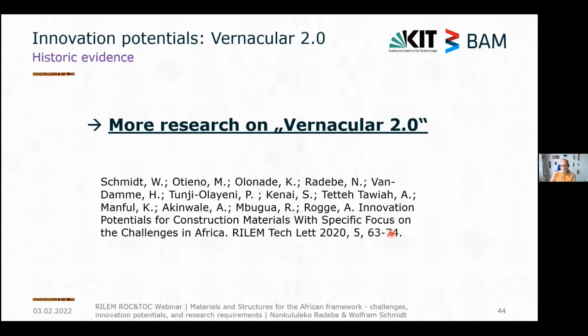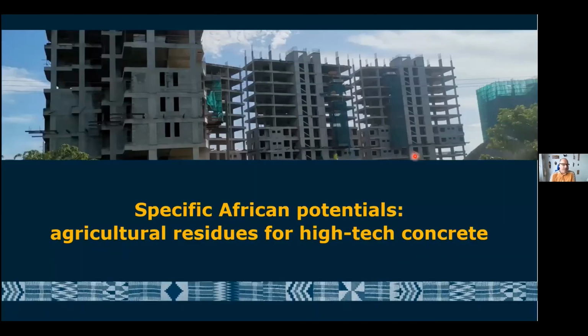But we certainly have to also not only understand the vernacular structures, but we also have to develop them further. This is what in the RILEM Technical Letters we call vernacular 2.0. We have to use modern analytics, modern knowledge in order to enhance these materials without giving up on their natural concept. And this, for example, is something where we can use vernacular structures. We can certainly use a steel reinforced concrete skeleton for structure, but we can fill it with vernacular materials. That would be a very good approach towards sustainability.